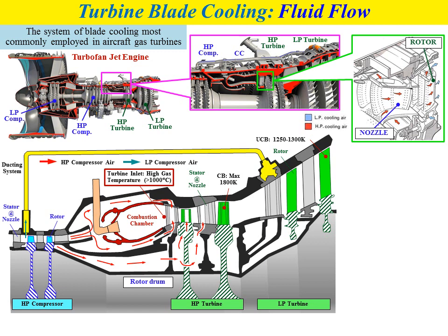For the low pressure cooling air, the cooling air comes from the low pressure compressor, where this cooling air will flow through the ducting system, and the temperature is approximately 400 to 450 degrees Celsius. If you look at the value, the temperature is already high.